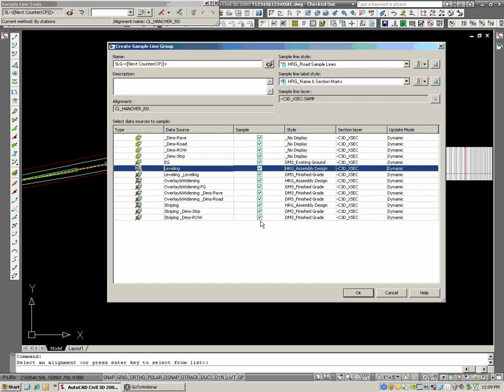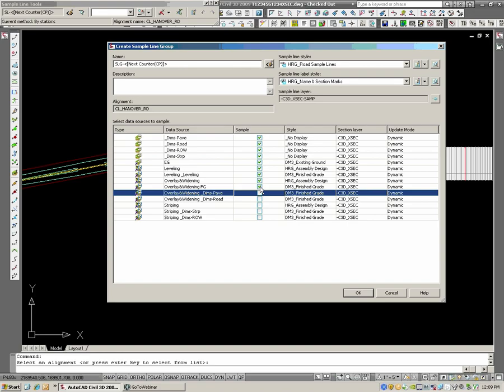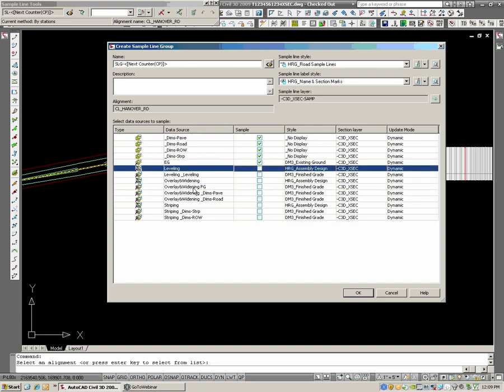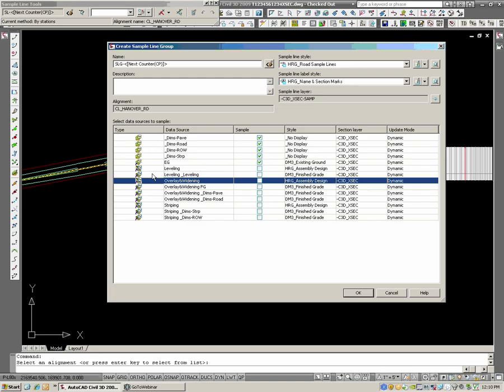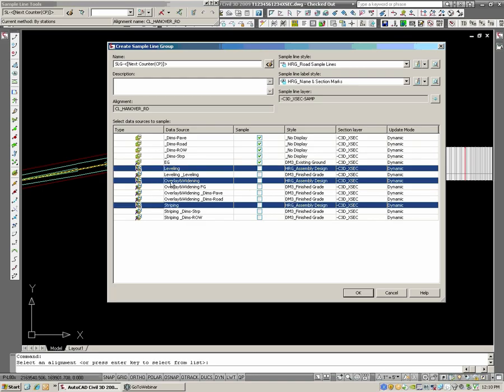And I'm going to go down through here and just uncheck all these corridor objects. The only thing we want to show, and this is the subtle difference I really don't like, is this piece of information and this piece of information, and these are the actual corridors. If you really look tight, and I wish I could zoom in, but I can't with the webinar software, you can see the road is sort of wide and you can see the little white dash in there. That's what's keying you in that it's a corridor model.